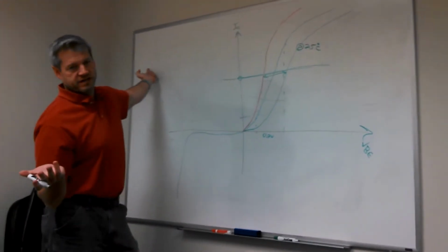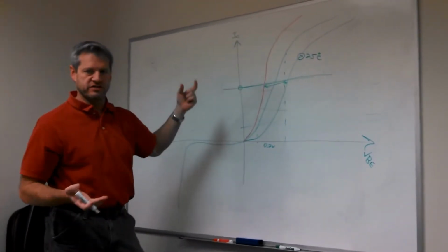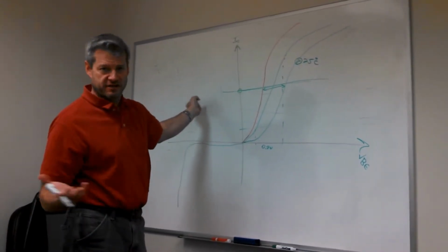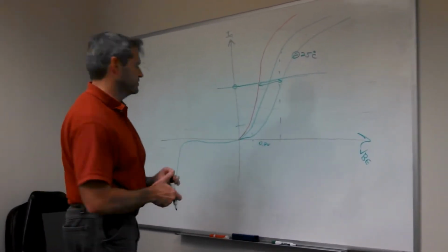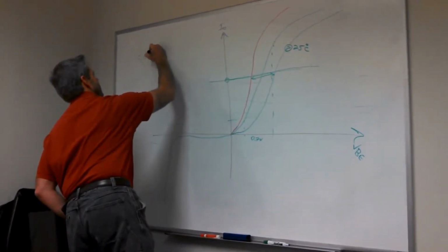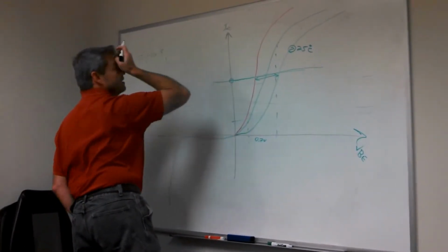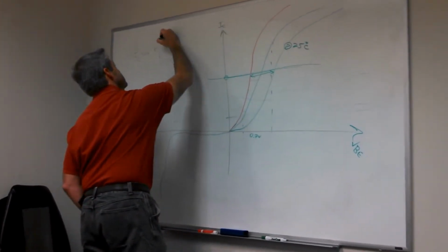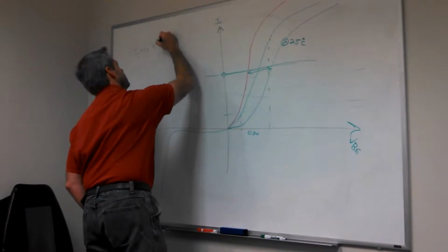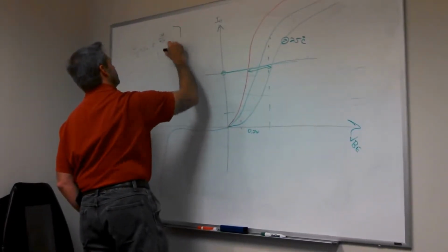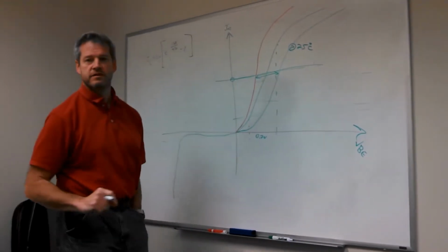For a transistor it's IC, but we're diode connecting our transistor, so it basically is a diode. So use IC, the collector current, even though there's no collector per se on this. Okay. So IC is equal to IS times e to the VBE over NVT, minus 1, right? I think that's what I said in the other video.